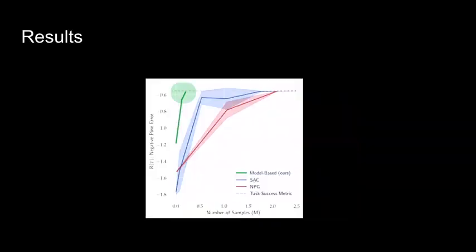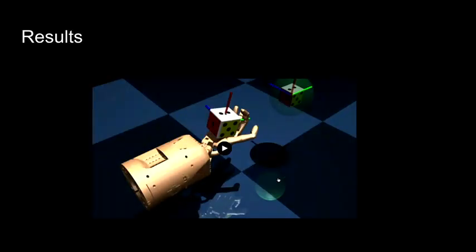So for the rotation task, if you learn a model for 90 degrees, 180 degrees, it generalizes to other parts of the state space, because it's trying to learn a partial model of what it means to rotate. It's not trying to learn a trajectory. So we are getting access to a dynamics model that you can retarget by changing a cost function later, as long as your state visitation roughly remains the same. If the state visitation differs too much, you can't do much. In the case of the cube that I showed, we did a lot of side turns, this turn, that turn, and it generalizes to other turns that we have never shown data about.